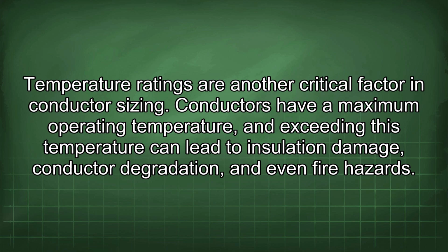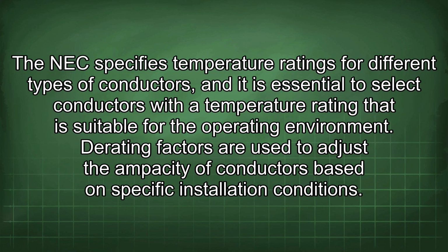Temperature ratings are another critical factor in conductor sizing. Conductors have a maximum operating temperature, and exceeding this temperature can lead to insulation damage, conductor degradation, and even fire hazards. The NEC specifies temperature ratings for different types of conductors, and it is essential to select conductors with a temperature rating that is suitable for the operating environment.